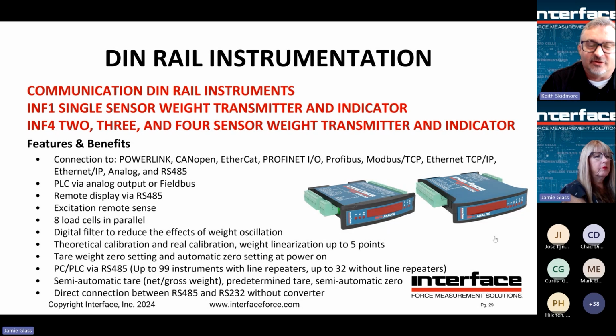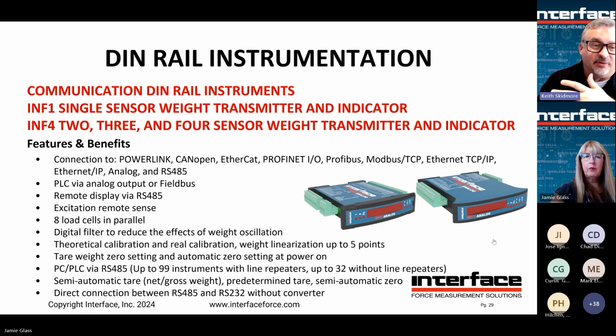Yeah, that's a very good question, and it can be a limitation. These INFs sample at 600 samples per second, so certainly not going to be any faster than that. And then there's some latency. Typically, it's on the order of a couple of milliseconds for the INF1. And then the IO-Link, 200 samples per second, and I think that's about a 50 millisecond latency on those. So they're great for certain things, and terrible and not going to work for other things. If you're doing impulse testing or something, they're going to be way too slow. So good question.